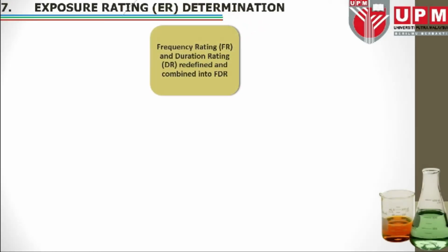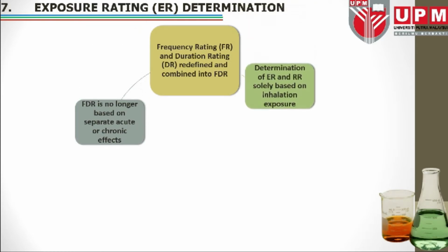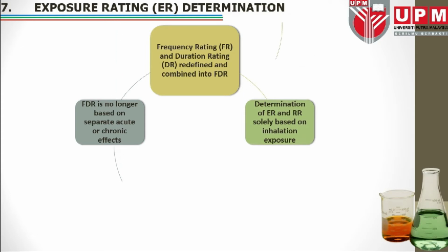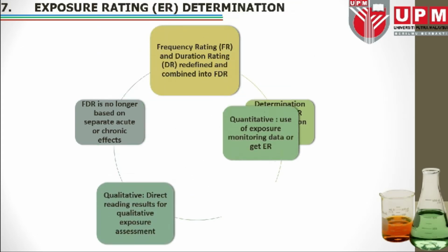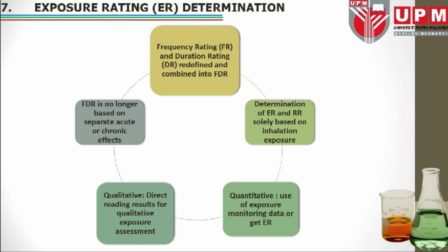In the 3rd edition, frequency rating FR and duration rating DR are redefined and combined into frequency duration rating, which is FDR, and this FDR is no longer based on separate acute or chronic effects. To evaluate exposure for inhalation, there are 2 categories: quantitative evaluation and qualitative evaluation.